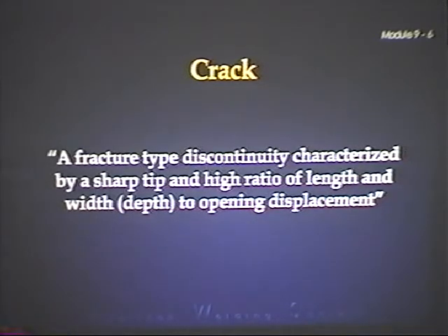So if you strike in front of wherever you're going to weld, drop back, pick up your puddle, and then weld on over it, you're going to remove any of that cracking. But if you strike outside the joint and then move into where you want to weld, you're going to leave all those arc strikes and all those little micro fissures in there. And incidentally, if you happen to do that while you're welding to the API 1104 code, that's going to be a cutout because it's not allowed. And you're going to get about 2 cutouts before they're going to run you off because they won't keep you on if you're sloppy like that. Arc strikes are sloppy.